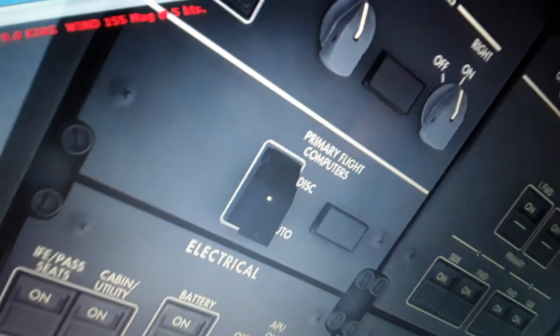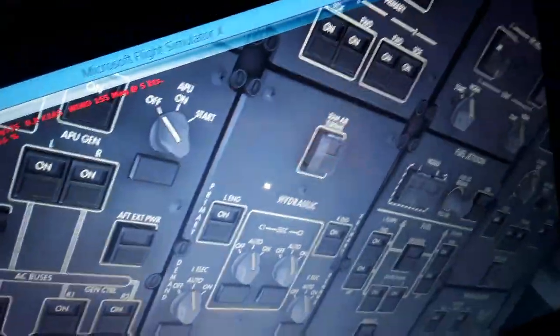I will show you the flight control computer. So you have the normal, the alternate, and the direct load, like in the Airbus aircraft of the flight control computer. So it degrades when you have failures from normal to alternate or direct. You have also the mechanical backup load. So you have here the hydraulics.